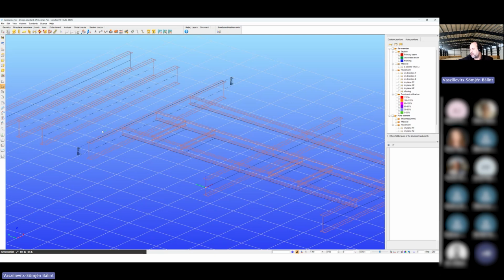Actually, mathematically it doesn't really matter, but to work with all the boundary conditions, supports, hinges, and others, sometimes modeling where the reference line is strongly outside of the section gives very strange, unaccepted results that are difficult to control. So it's much easier, even if we work with eccentricities, to always have the reference line as close as possible to the original center of gravity of the section.